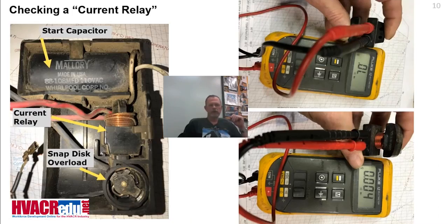If you pull the circuit breaker out, if you're allowed to do that, I'm not saying that you are, but if you're allowed to do that, I won't be surprised if you find that the clip that goes on the bus bar inside the panel has turned brown, all right? Because it's been heating. Heat causes conductors to turn colors, okay?